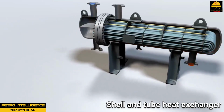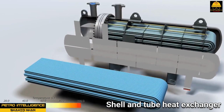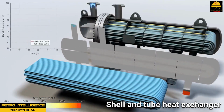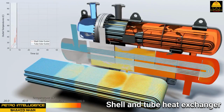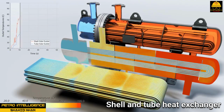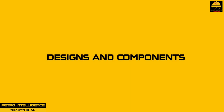Fluid flow into and out of the heat exchanger is designed for specific liquid vapor services. Liquids move from the bottom of the device to the top to remove or reduce trapped vapor in the system. Gases move from top to bottom to remove trapped or accumulated liquids. This standard applies to both tube side and shell side flow.